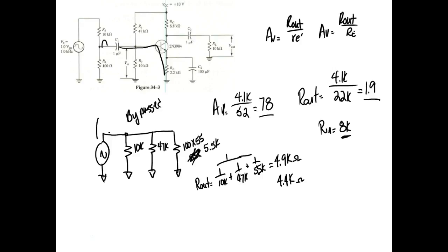So what I would like to do is match a high output impedance to a high input impedance. And a common emitter just doesn't do that unless we do what? Unless we deliberately swamp it, is what they call it. You deliberately reduce the gain. So if something happens to this capacitor right there, my gain is going to go way down. I'm still going to get gain, but it's going to go way down. That's basically what we're trying to do, figure out what's going to happen when different things go bad.